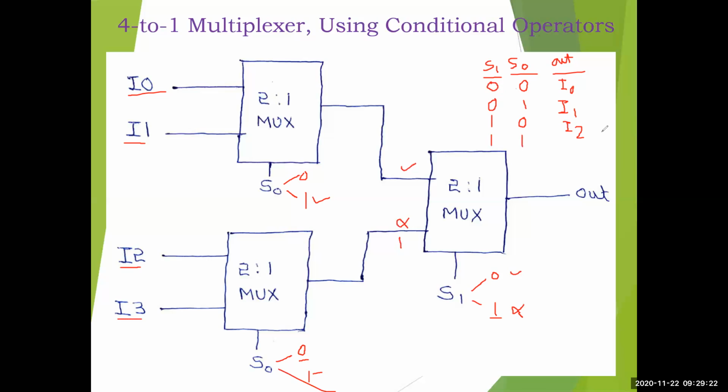So see this design of 4:1 mux using 2:1 mux. Now the same one is modeled as nested conditional operators. Hope this design is understood to you. In a similar way, a 16:1 mux can be designed using 4:1 muxes, or 2:1 muxes. The basic block in a multiplexer is the 2:1 mux, remember this. The very basic block in a multiplexer is 2:1, so from that you can build any number of muxes. That is the idea. Hope it is understood.